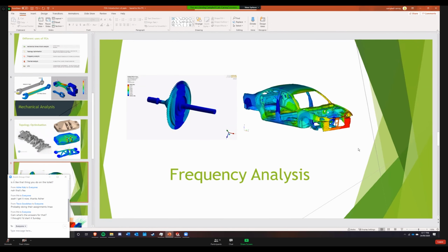And then on the right-hand side, you've got your vehicle. So you can imagine if you're driving down the road and you start hitting a few bumps, and then your vehicle starts doing this, you get excessive movement in these low support sections, which is obviously very bad, because you do not want your vehicle to do this. It should be rigid enough that you can drive it down the road without a problem. So understanding the natural frequencies of a system is very important.